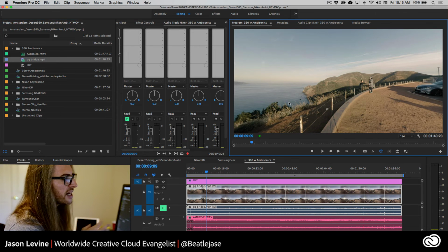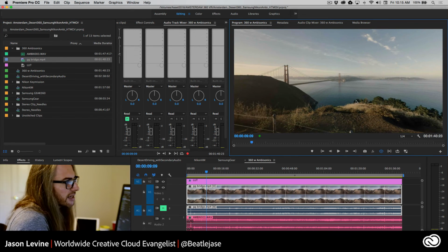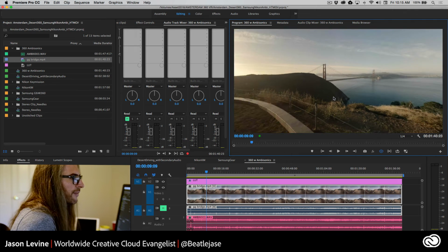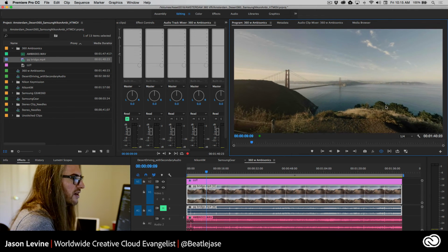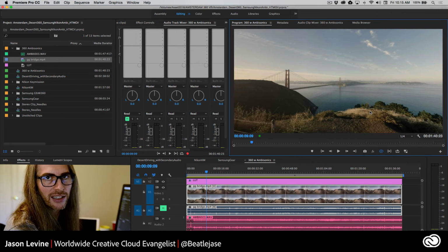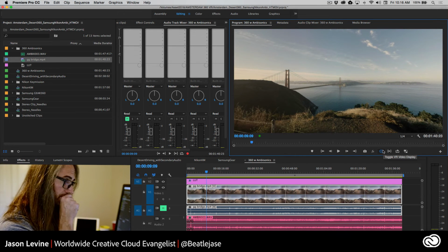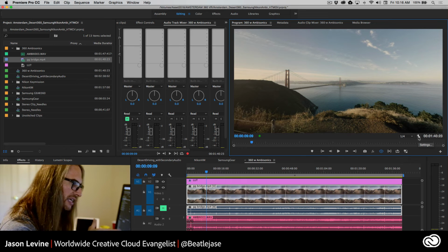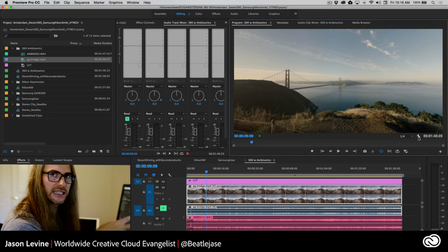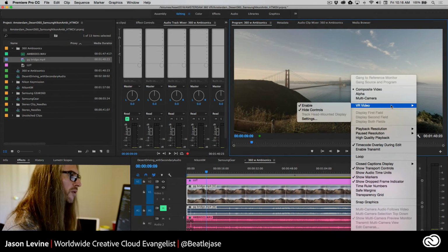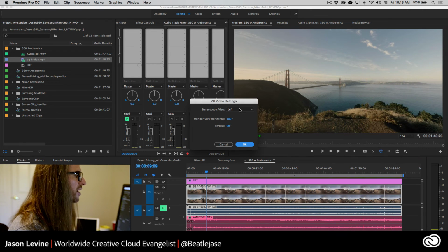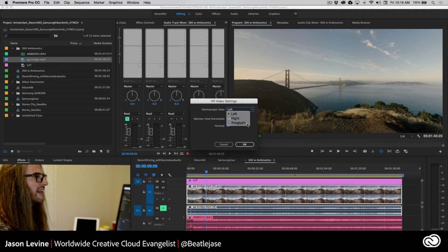So here inside the viewer, this looks like, again, just regular 360, right? Well, that's because we're not viewing this in a stereoscopic method, namely the anaglyph preview method. To actually preview the 3D stereoscopic flavor of this inside the program monitor, click on the wrench menu here, go into VR video, under settings, and you'll see under our VR video settings, we can choose anaglyph.